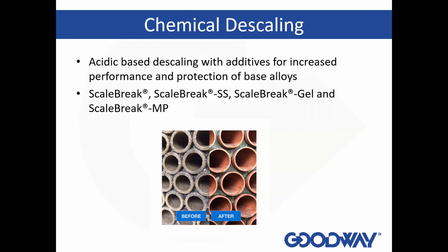They go in and strip away the insulating layers in boilers, and at the same time they're formulated with heavy corrosion inhibitory packages. So they're acidic, but they're biodegradable, and there are buffering agents in there that are good from an environmental health and safety standpoint. But it'll do the job. It'll go in and get rid of the scale and corrosion byproducts and tuberculated iron and everything else that's residing inside the boiler, while also being very safe from an environmental health and safety standpoint.